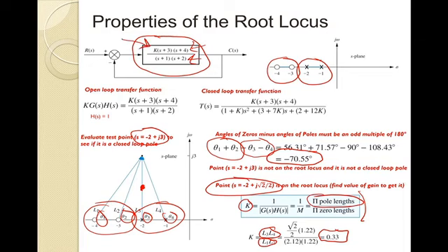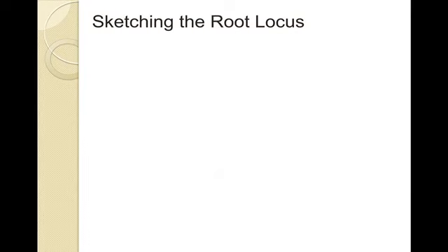transfer characteristic such that when we draw the root locus, as we look at the root locus based on this open loop criteria here, that these two poles would come together and then go off axis here, and then there would be this point right here at negative 2 plus square root of 2 over 2 that would be on the root locus, again at that gain of k equals 0.33.